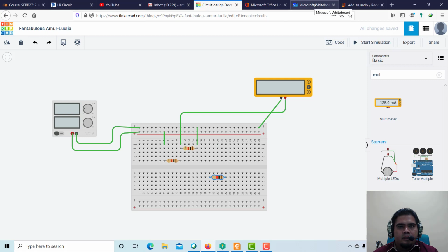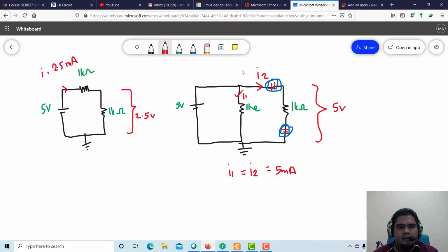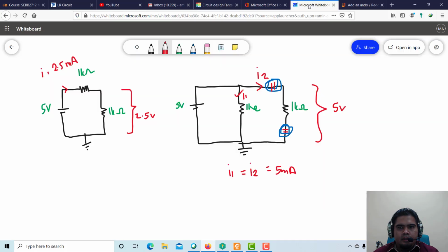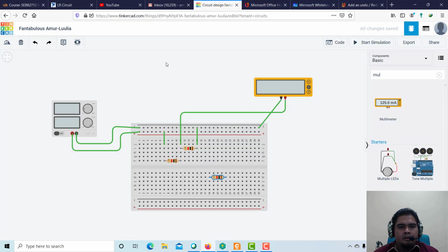If you refer to this schematic, row number 18 here should be this one, because it is connected with your first resistor, which is R1. Now we want to connect this row number 18 with the positive terminal of the power supply. So where is the positive terminal of your power supply? It is this line. Then I just take one jumper and connect it with row number 18 there.